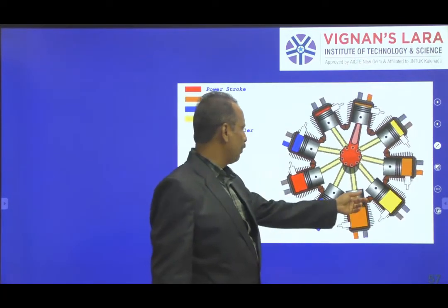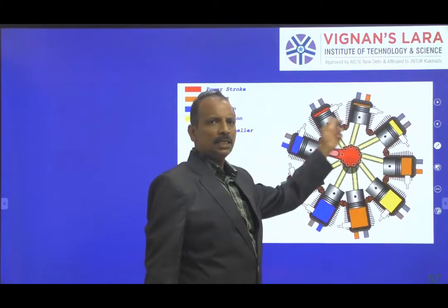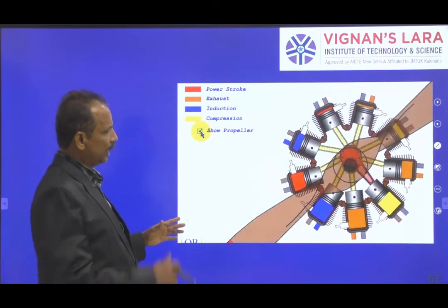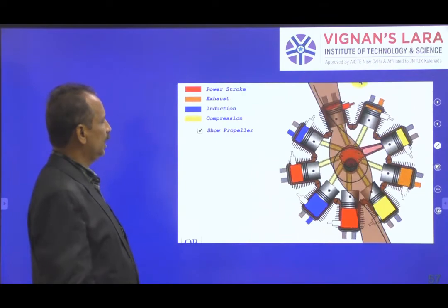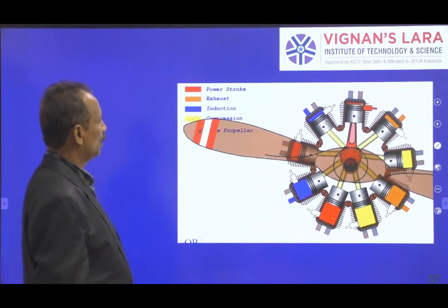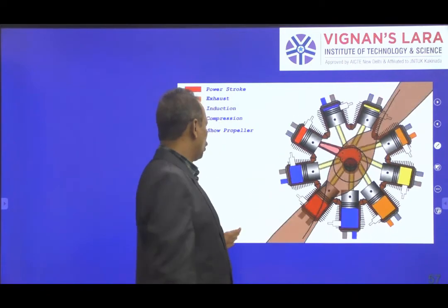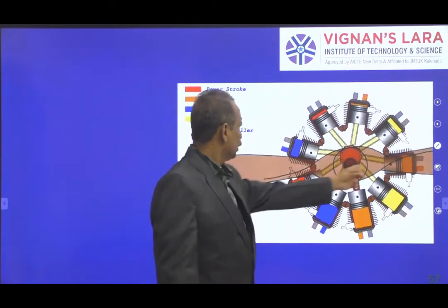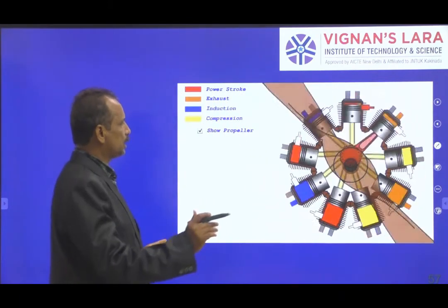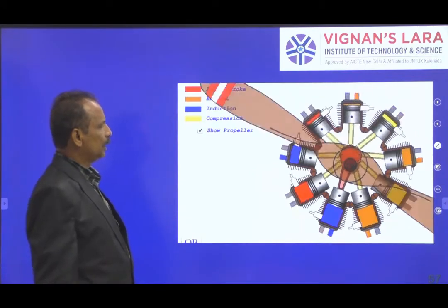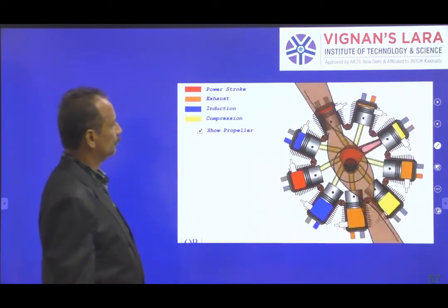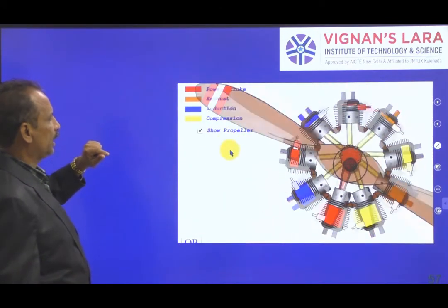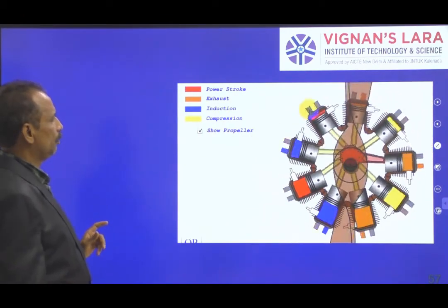You can see here what is happening. The entire engine is revolving. That is a rotary engine. Okay, so where the entire mechanism or the entire cylinder is revolving. So this motion is given to the propeller. That is what he means to show, because these are the blades, or whatever you call it, driving one. The entire power is given to this propeller. So this is another inversion of the single slider crank chain by fixing link number 2.